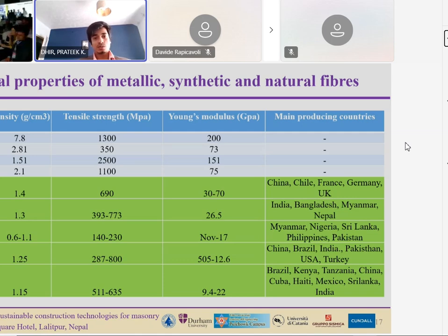render properties. There is a lot of literature available on different kinds of fibers we add to the mortar to enhance the properties. Definitely the steel, aluminum, carbon, and glass fibers provide really high tensile strength and really good performance. But we are trying to go with some natural alternatives. When we investigated the alternatives, we found many good options like hemp fiber, jute fiber, and sisal fiber. And it's not about choosing the fiber, it's about the overall cost.